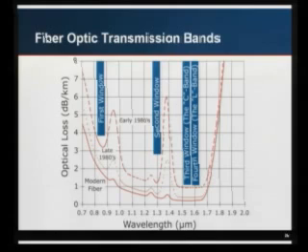And you can see there's what's called water peak, these big peaks where the spectrum's completely unusable because of how much it absorbs. And you can see as they've progressed through fiber technology, they make low water peak fiber now that has very little issues. It works basically like the most optimal bands, but this shows the relative positions of the bands and why they were chosen.